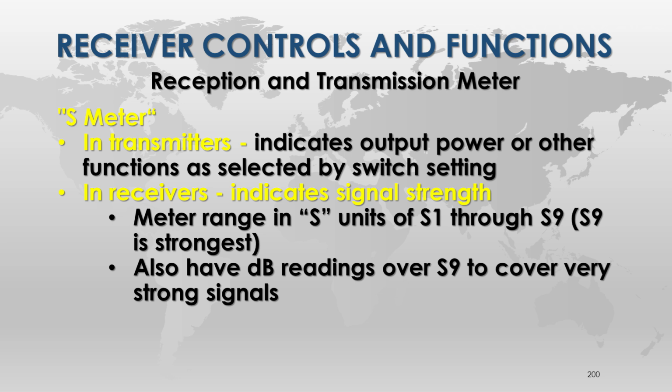That's the deceptive part about repeaters. When somebody asks for a signal check on a repeater, regardless of how they phrase it, what they're actually looking for is how's their audio. KG7TU, can I get an audio report, audio check? Hey, can I get a signal report? And somebody comes back with, yeah, you're 5 by 9. You know they don't understand the system, because you cannot be 5 by 9 on a repeater. You're only hearing the quality and signal strength coming out of the repeater.